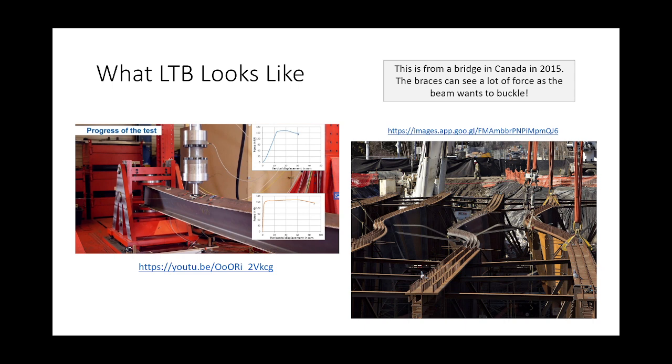But it's not moving to the left or right. What happens right here, pew, it goes. Did everybody see that? It goes pretty quick. The load is really not increasing very much, but it's undergoing this uncontrolled lateral displacement, and it's going pretty quick. You can see what it's doing: that whole kick out and twist thing. So this is the effect. This is what lateral torsional buckling really is. When it happens, it can happen very suddenly. All buckling phenomena tend to be pretty sudden failures, characterized by very large and very sudden deformations. So there's some serious stuff going on that you need to account for.